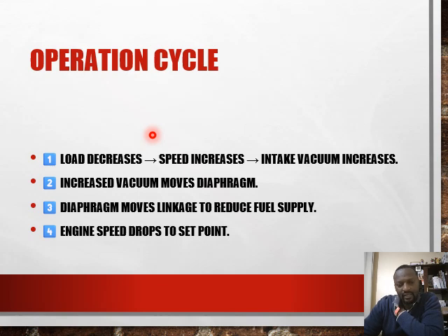Now, as the engine speed increases, the throttle valve is opened gradually, and therefore the vacuum that was there now starts to decrease, or starts to collapse gradually. And as this happens, it means that now the return spring overcomes the force generated by the depression, and at any given speed, the position of the rack is a result of an equilibrium created by the spring tension and the depression created at that speed.